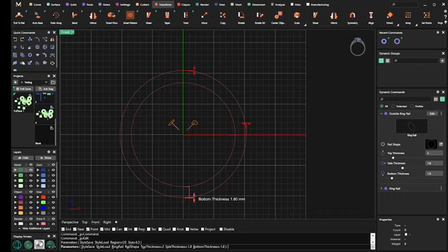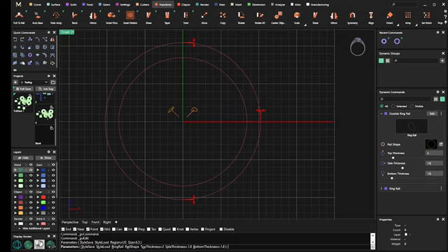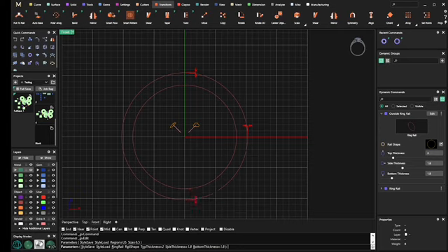There's some that I use consistently, and I know that it's going to give a really good result if I use these tolerances. So sometimes what you see me do is just what I'm comfortable with, making good jewelry that's going to last for a very long time. It's a little thick, but if you did 1.8, that gives a very nice bottom or back of the ring. I will do the 1.8 or even more if the ring is top heavy.